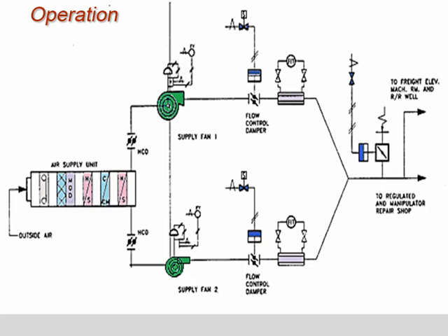The air supply units, or ASUs, draw air in through filters. If drawing outside air, it will first pass through a roll filter and then a mod filter. After filtration, the air is heated and cooled as needed to maintain temperature and humidity. The system fans move the air through the system. Flow control dampers are used to maintain flow to various parts of the building or facility in proper proportion. Flow meters are used to monitor airflow and may position dampers automatically.